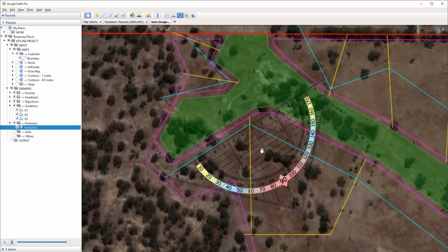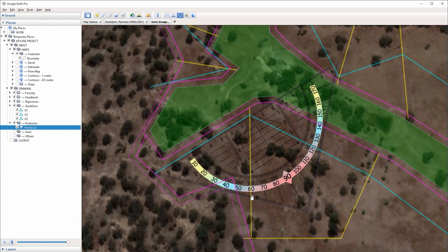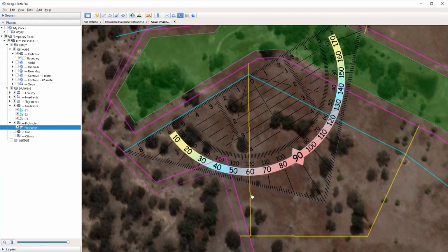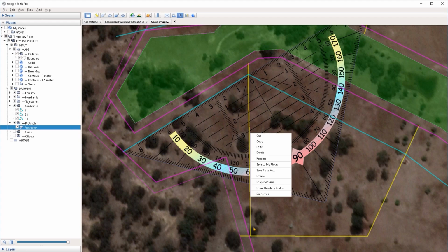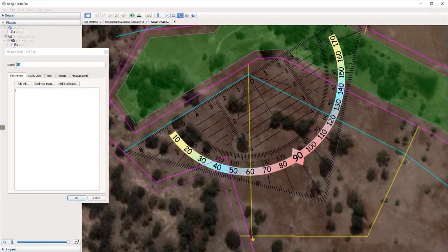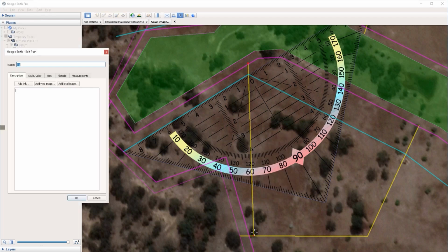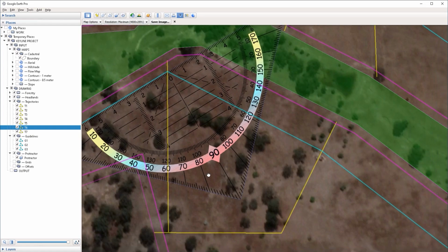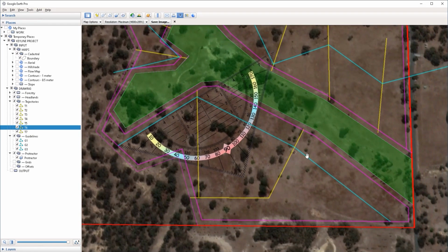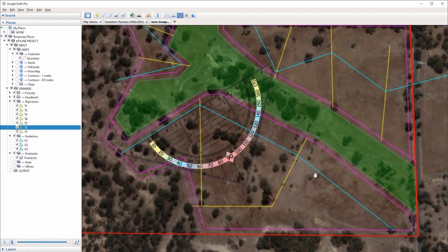So the middle of our angle is going to be exactly at 61 degrees, which is at 61 right now, I think, or it's going to be somewhere around here. So I could just press the right mouse button directly on top of the yellow guideline to access its editing, and then I'm just going to left click, hold and drag on the endpoint to position it into place. And now we have to repeat this process for every angle that we have on our guideline. In this case, we have just another one.